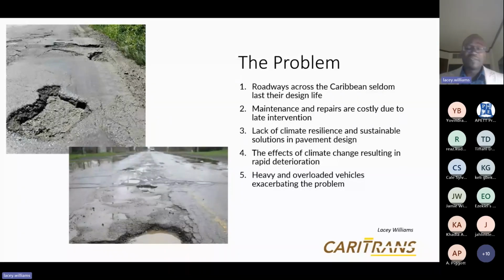Just to close off this point, I did an axle load survey, a heavy vehicle weight load survey somewhere around the COVID period, and based on the loads that we would have encountered, we did not expect the pavement life to exceed 7 years for a 20-year design life for that particular road pavement. So in other words, the client would have spent tens of millions of dollars in reconstructing the particular roadway, with the only expected benefit being that it would last for perhaps 7 years at maximum.